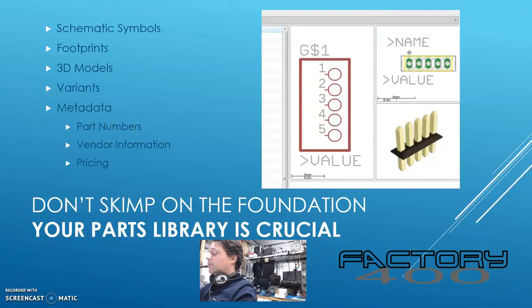That way I can spit out a bill of materials that's accurate for my own internal parts. I can see what I have, what I don't have. It will also have the vendor part number, so for the ones that I don't have, I can go to DigiKey and make up an order fairly quickly. It also helps me when I'm storing the parts. My part numbering system is a separate video altogether, but I wanted to make sure it was completely integrated in Eagle, so that when I go to assemble the boards and all of that stuff, every time I pick a part that goes onto a board, I'm able to track it, I'm able to understand it, I know how much it costs. Those are all really important elements.